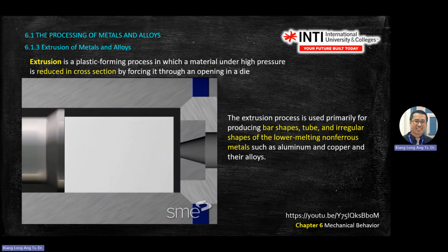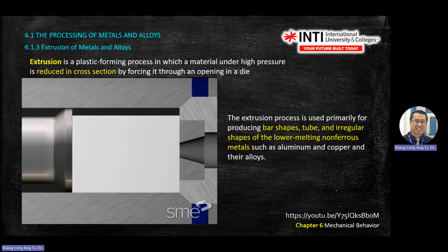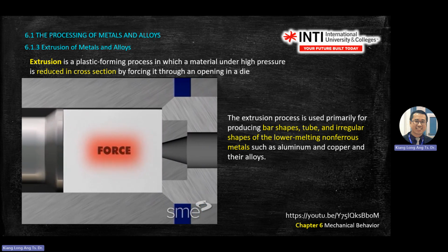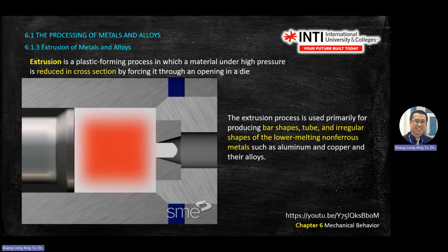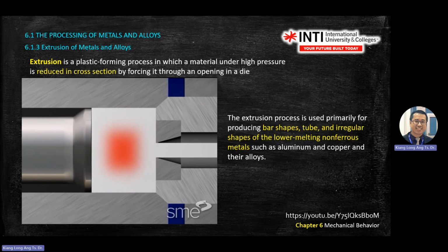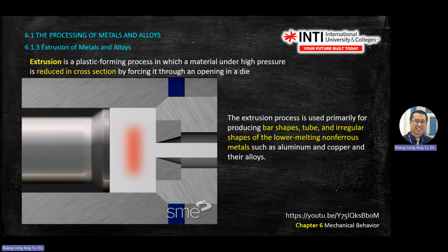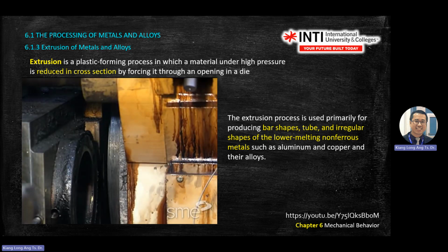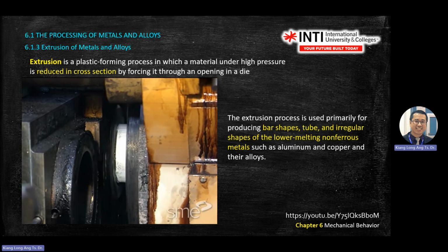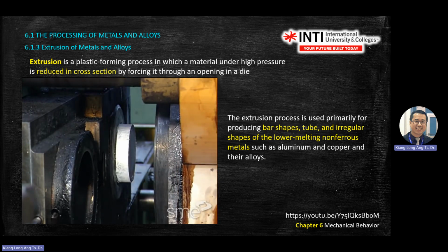Force increases rapidly as the billet is upset to fill the container, then increases further as breakthrough force before extrusion begins. Upon breakthrough, the force declines as billet length decreases until a minimum force is reached. As the billet thins, heat generated rapidly rises, and metal continues to flow radially toward the die opening. So when you design this, you need to be careful about the material expansion. Resistance to deformation and force requirements will increase markedly as the thickness of the butt or unused billet portion decreases.